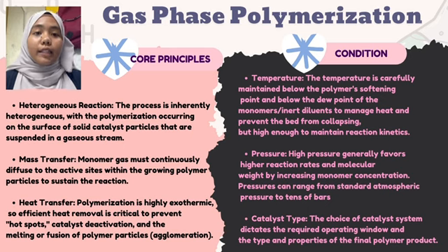The second one is pressure. High pressure generally favors higher reaction rates and molecular weight by increasing monomer concentration. Pressures can range from standard atmospheric pressure to tens of bars.